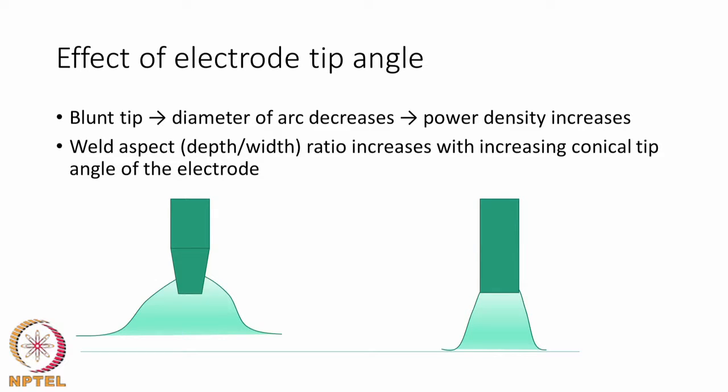You can see that the shape of the arc looks like a decreasing profile, with the maximum value under the electrode and going towards 0 away from the electrode. The width of the arc is generally slightly more than the electrode, maybe up to about 2 times the diameter of the electrode. It is also possible for the electrode to be either sharpened to a tip, or conically tapered, or just blunt.